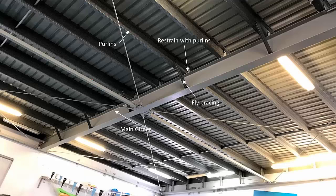So here is an example of an actual beam. As you can see, at this point it is connected to the purlin, and also the fly bracing is connected to the tension side as well, right? So this part cannot move laterally. We can consider this as a fixed section, a fully restrained section, and at this point it is also fully restrained. So we only have to take this length as the length of the segment, to take into account the lateral buckling within that segment only. We can see that there is full restraint on these sections here. Good. And at this point, it may not be fully restrained because there is no fly bracing. It is connected to the purlin, but it might be partially restrained at that point.